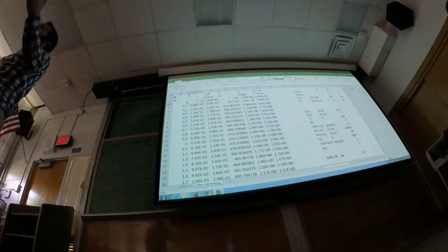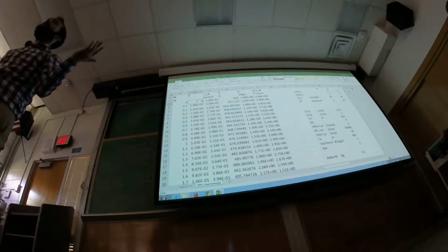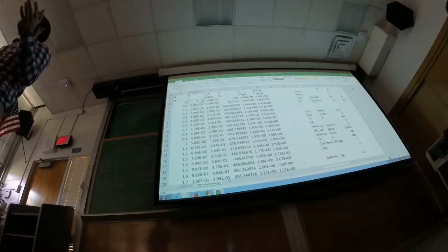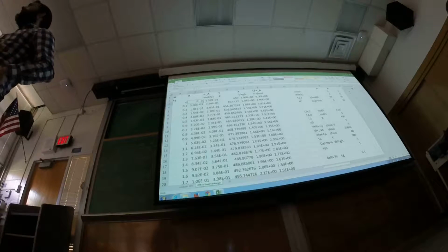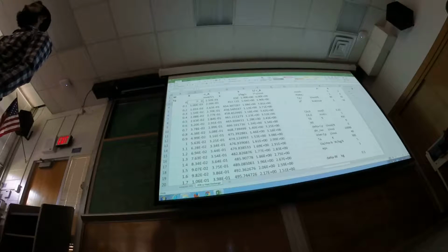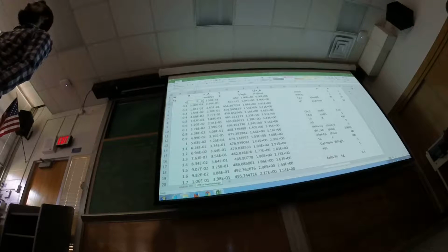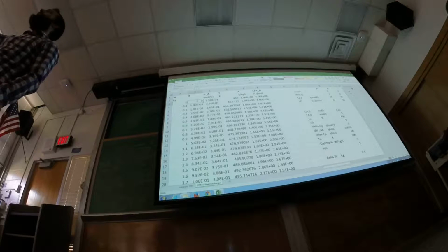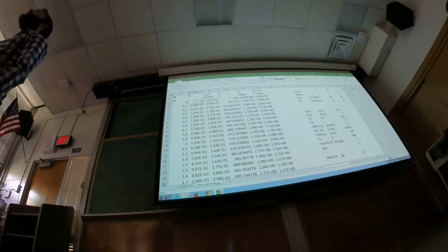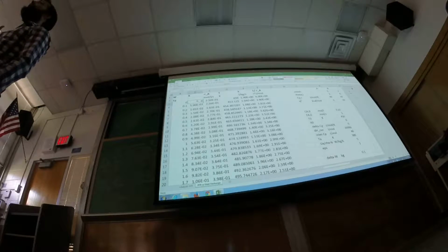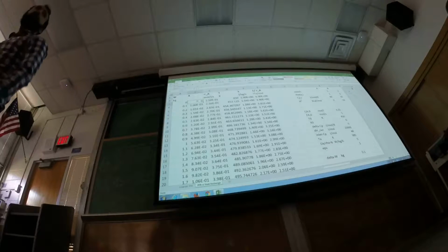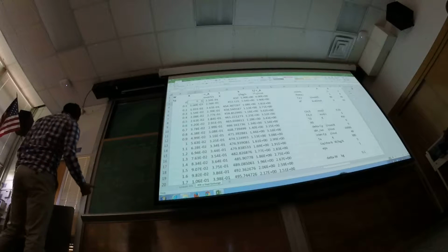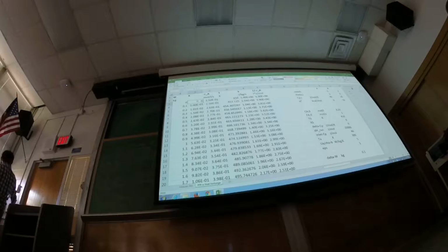Which one wins, right? How do we know? What's ultimately going to determine whether the temperature initially drops or initially increases? It's a competition between the rate of the reaction times the delta H of reaction. That's generating heat in this case, because it's an exothermic reaction. And now on the other side of that equation, we're removing heat.